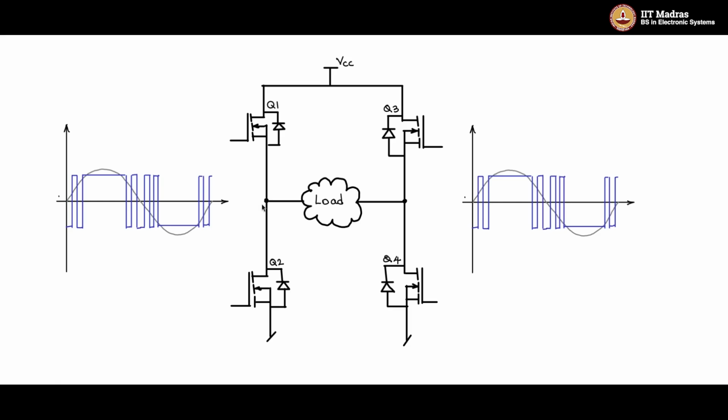So now if I have to get a pulse width modulated waveform here with a sine contained in the fundamental, then let us say I have this sinusoidal pulse width modulated waveform given here. On this side, with the same triangular carrier, if I give a pattern like this, what will happen? This minus this, you will end up with 0 fundamental.